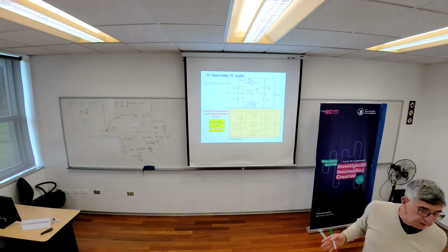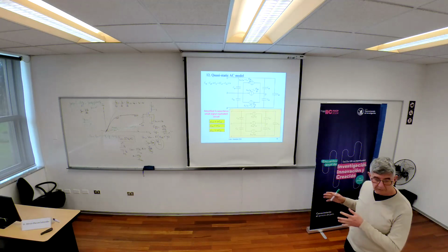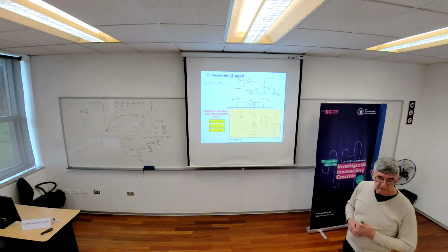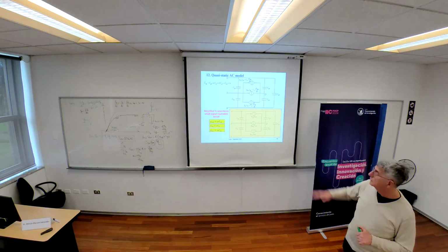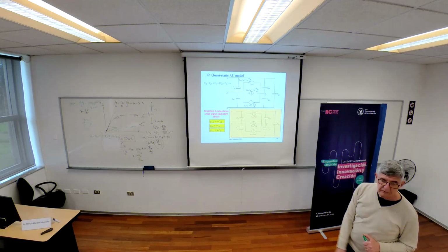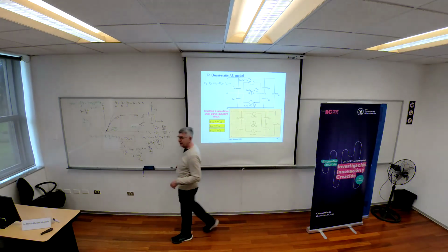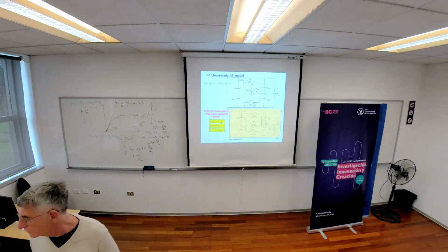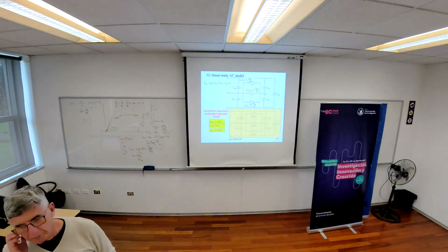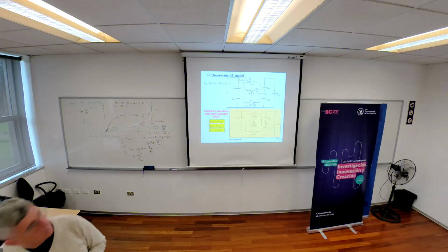Okay, so you have to make the DC analysis before the AC analysis, of course. You should know the operating point of the circuit in order to calculate all these parameters. Okay. This is a big issue. First of all, you have to solve the DC equations of your device, or to put this device in a simulator and find out what is the DC operating point.